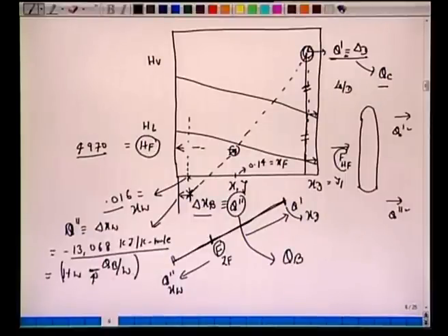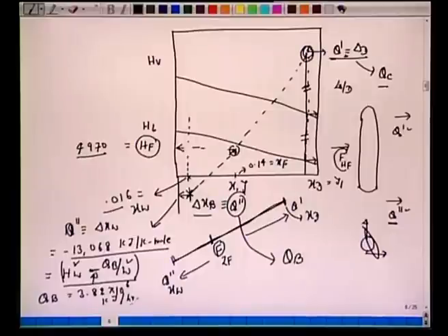So we had that discussion earlier. This is hW minus QB by W, the enthalpy of this stream, hypothetical stream, which leaves with this Q''. So knowing hW, all right, again here we have the boiler, this liquid and the vapor, they are in equilibrium, saturated. Okay. So knowing all these quantities, hB, W molar flow rates, Q'', which we have calculated, one can calculate boiler load as 3.82 × 10^6 kilojoule per hour.